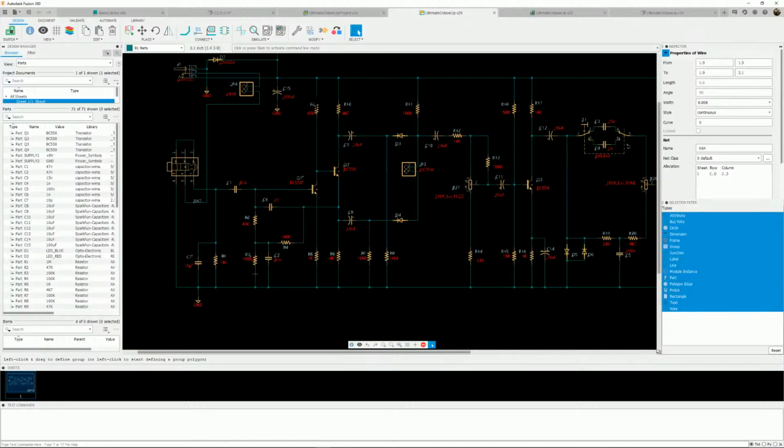But the DC bias comes through this 47K pull-up on the second transistor, the 0.6 volt drop there, through this 100K and the pull down there. And then this circuit here provides some AC feedback characteristic. So it's a bit of a filter as well.